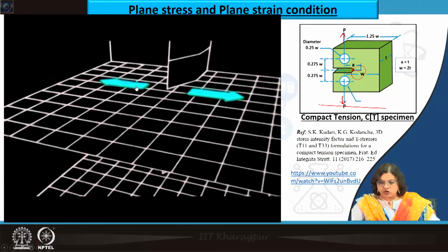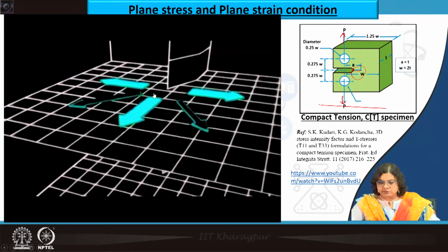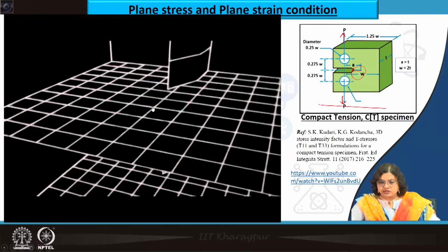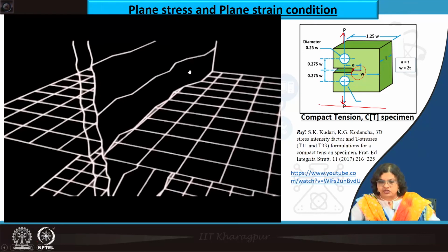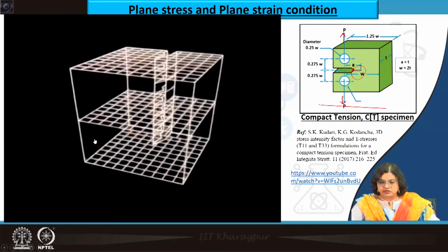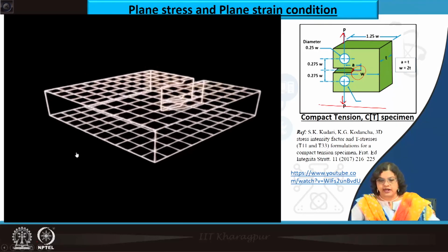So, if we are talking about the fracture surface, these are the stresses that are being applied, tensile stresses, and there are shear stresses along 45°, but since these tensile stresses are mostly active, the fracture is happening along this way, which is leading us to flat fracture.